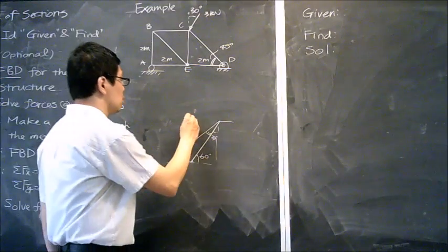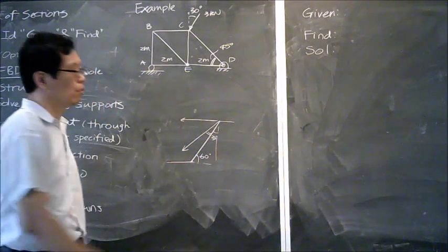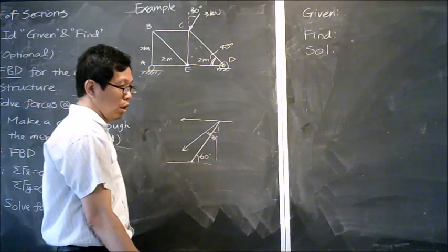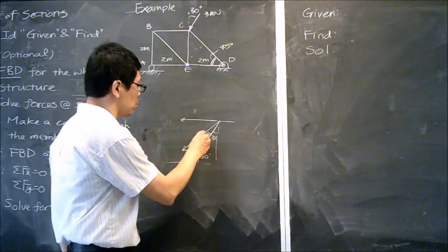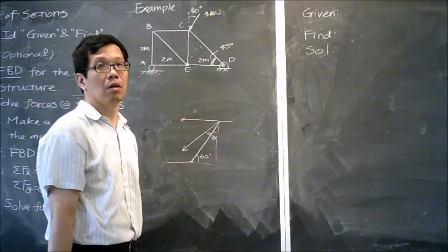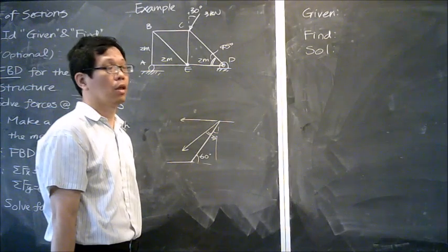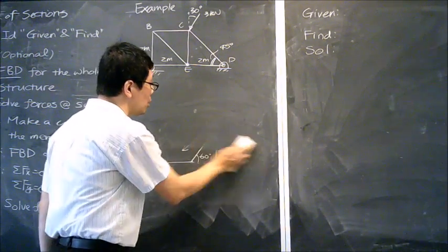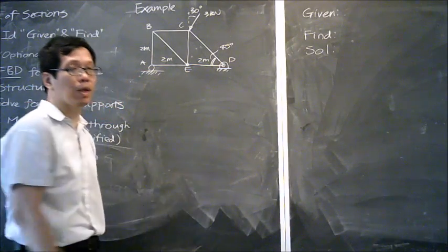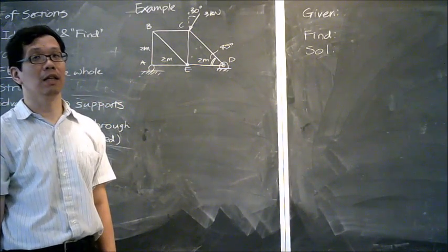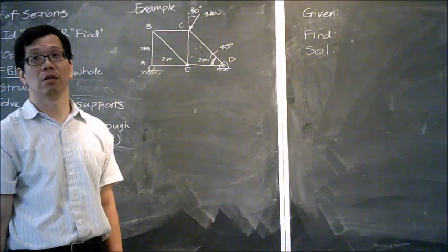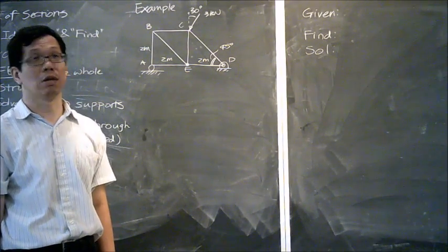And there are two combinations of forces over here, and I ask you to get me the resultant. For some reason, a lot of you guys just assume this is going to be 30 degrees, which is not correct. So when you are doing those kinds of things, just be careful. If I didn't specify the angle, then it's not the angle you see in the configuration. Don't just assume, do the calculation, okay?